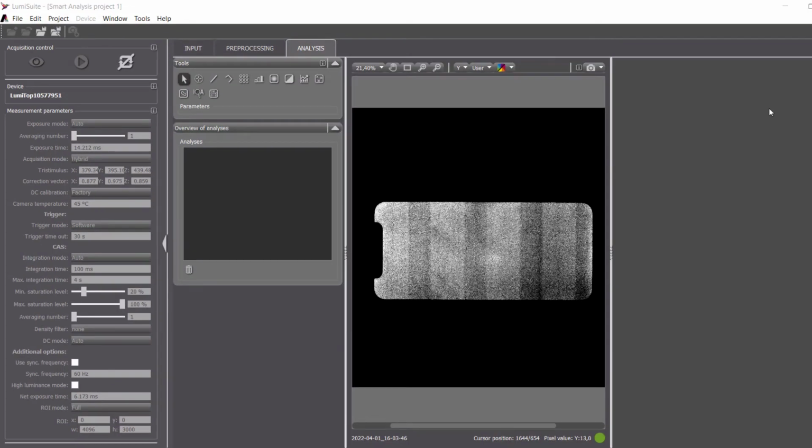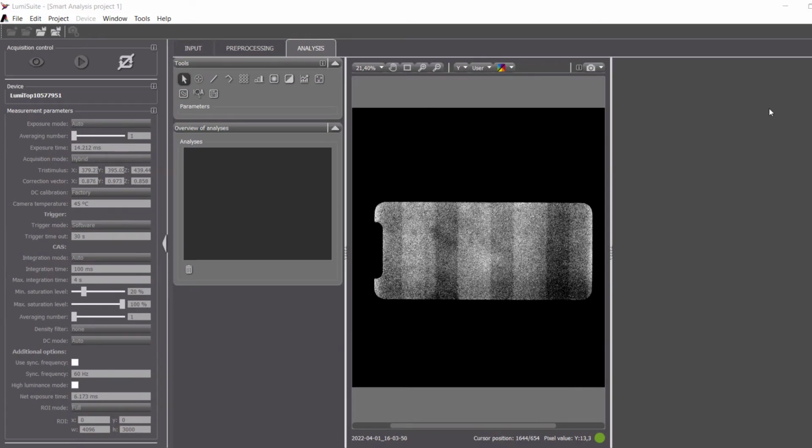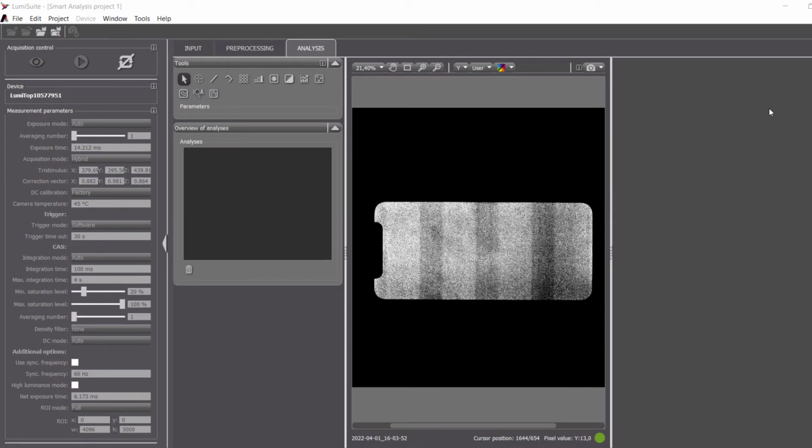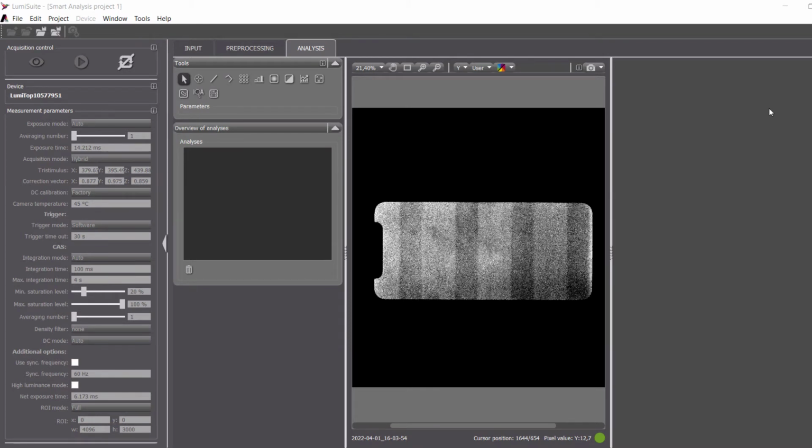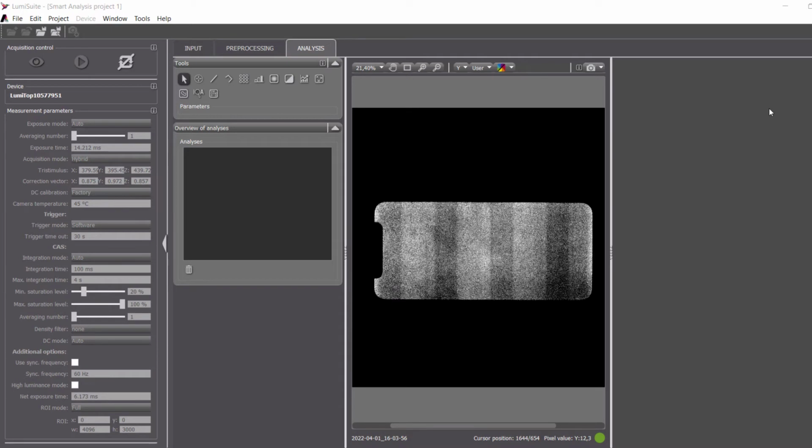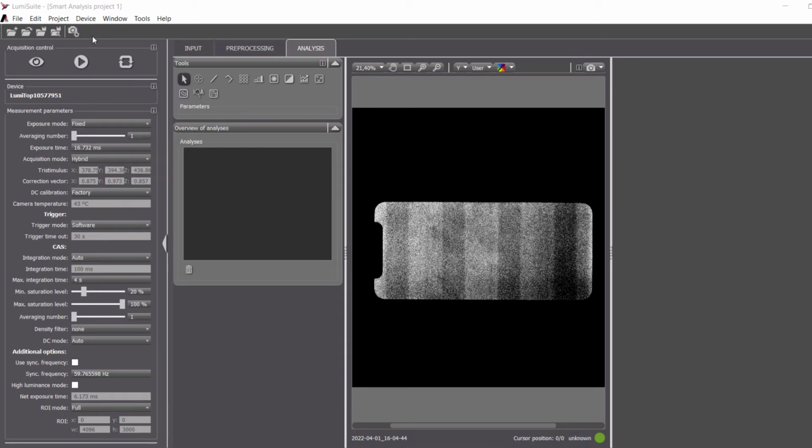This occurs because the display is modulated with a specific frequency, and for artifact-free measurement, the exposure time of the camera needs to be a multiple of the refresh time for the display. To ensure that the exposure times are matched to the refresh time, first we need to measure the refresh rate.